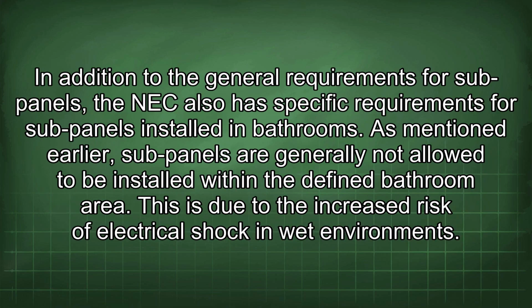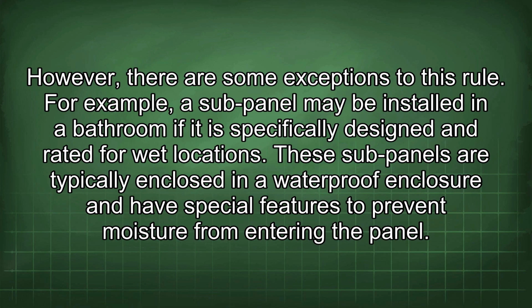In addition to the general requirements for sub-panels, the NEC also has specific requirements for sub-panels installed in bathrooms. As mentioned earlier, sub-panels are generally not allowed to be installed within the defined bathroom area. This is due to the increased risk of electrical shock in wet environments. However, there are some exceptions to this rule. For example, a sub-panel may be installed in a bathroom if it is specifically designed and rated for wet locations. These sub-panels are typically enclosed in a waterproof enclosure and have special features to prevent moisture from entering the panel.